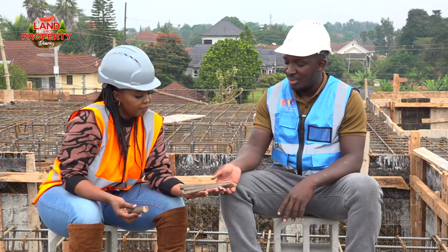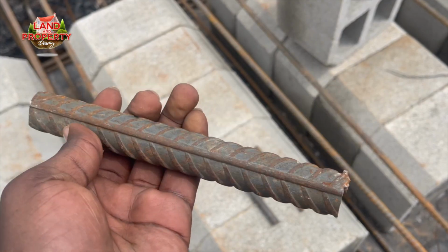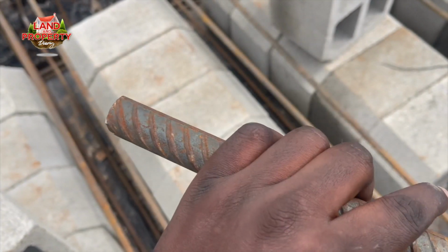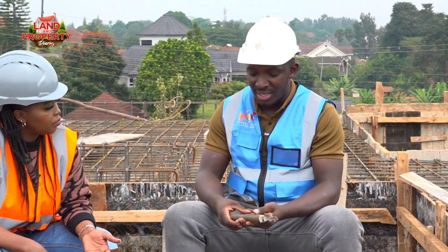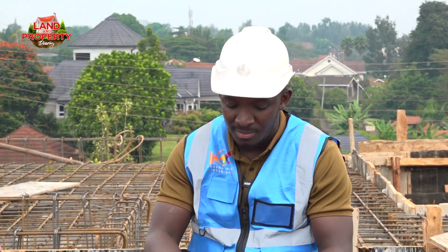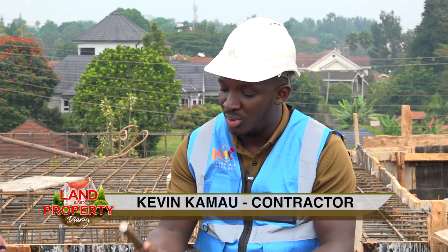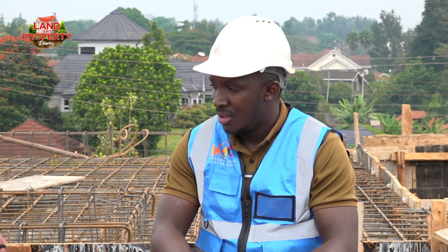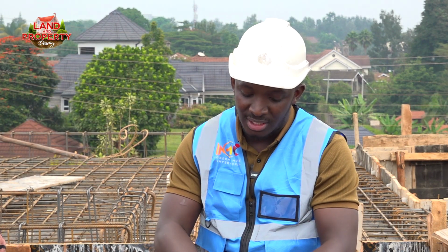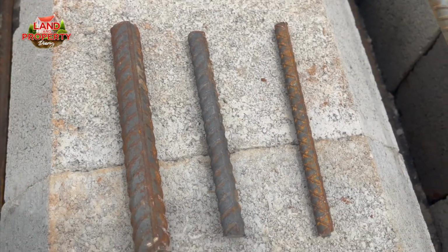So all these reinforcements are used for different purposes. For example, if you have a very big building and it has very big beams, you might end up using this D25, like we've used in these beams. For columns, you can use D20 and D16. It all depends on the structural design. The structural design will guide you on what reinforcement to use where.